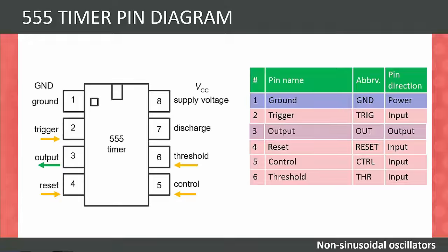It measures the time delay by monitoring the voltage across a capacitor. As a capacitor is filled up, it gets exponentially harder to fill. Once the voltage measures about 63% of the supply voltage, the timer will stop timing. This point is chosen because it is considered the straightest and thus most predictable part of the filling cycle graph. We'll see how this works a bit later.